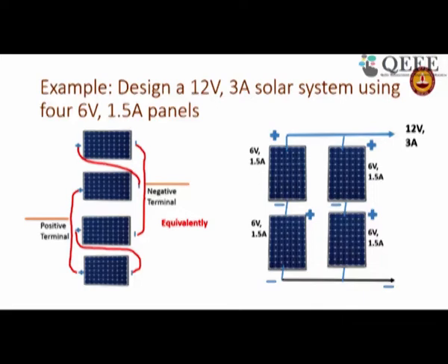So if you want a 48 volt operating point, you need to get something like a 40 or 42 volt solar cell. You need to worry about this. This is extremely important. So you have to design depending on what operating voltage you want. And remember, operating voltage will change with temperature and throughout the day.